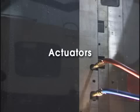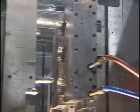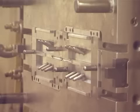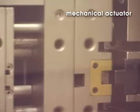Actuators move the slide into position before injection and pull the slide back before part removal. The three forms of actuators used are the mechanical, pneumatic, and hydraulic. The mechanical actuator is the most common and uses actuator pins, also known as horn or angle pins.